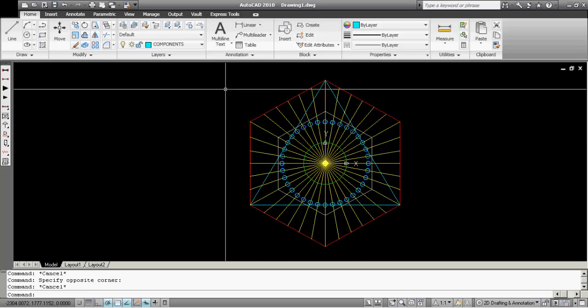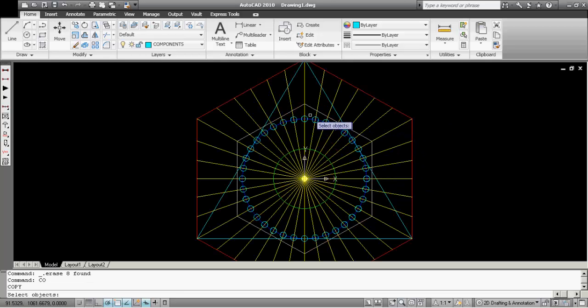A lot of the times though, your elements won't fit a rectangular window, so you can do a polygon selection, like if you wanted to select every other blue circle. For that you can use a polygon. You can use a window polygon or a crossing polygon.